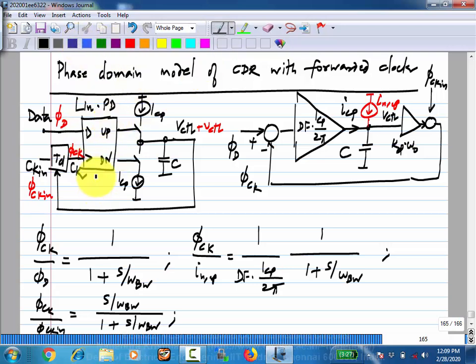So this phase detector also has the data output, right? The recovered data output. It is taken from one of the flip-flops in the phase detector. Okay. So you go on increasing the amplitude of the data until the bit error rate crosses a certain threshold. Maybe your threshold is, let's say, 10 to the minus 12, and you go on increasing the jitter until the bit error rate exceeds 10 to the minus 12. And you say that that value of jitter is what you can tolerate.